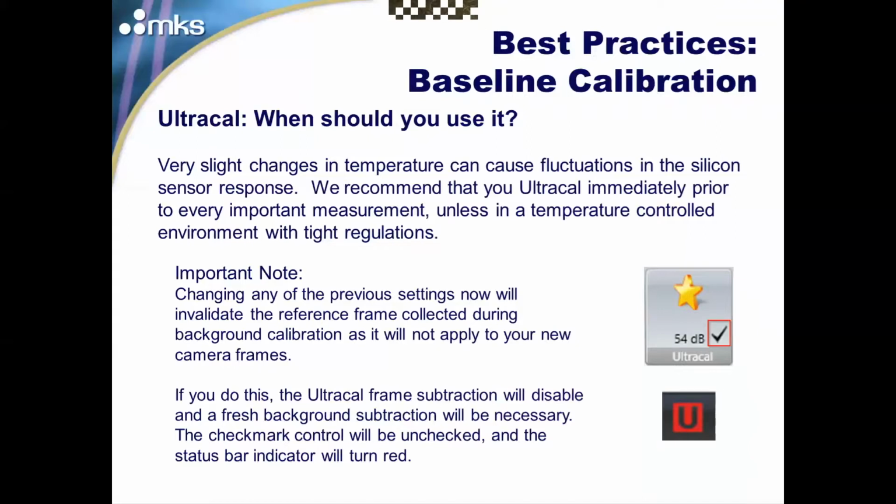So all in all, we recommend that you ultracal immediately prior to every important measurement. If you haven't done an ultracal in a moment, block the beam, hit it again, just do it, and that way your beam profile measurements are consistent every time because you're doing that calibration in a consistent manner.